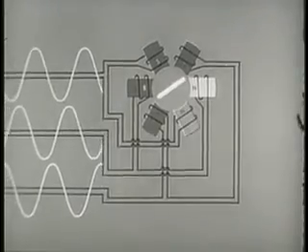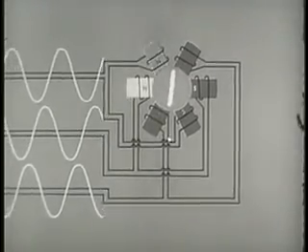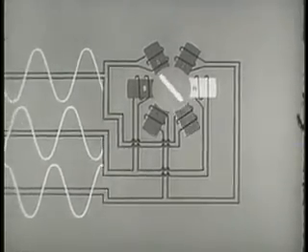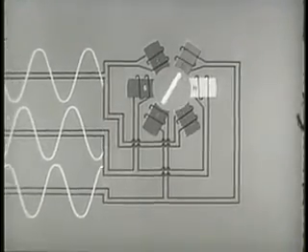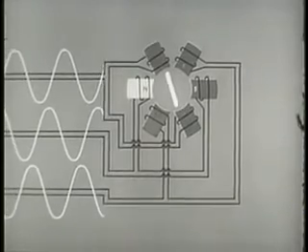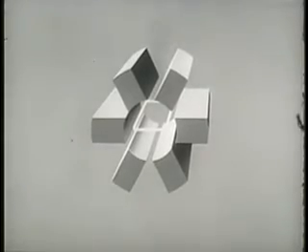You'll remember that the operation of the induction motor depended on relative motion, that is, the difference in speed between the rotor and the rotating magnetic field. This relative motion induced an EMF in the rotor. In the synchronous motor, however, a different situation exists.